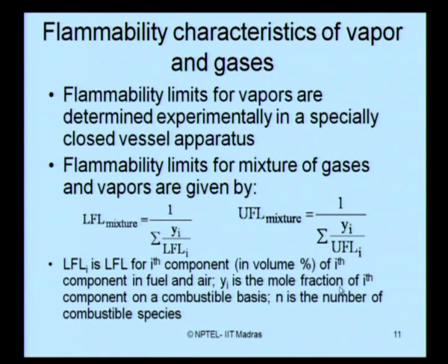So, if you have different mixtures, if you have the mole fraction of any component on a combustible basis, and if you know the volumetric composition of that in percentage in fuel and air, using this relationship of LFL and UFL for any given mixture, you can easily obtain the upper and lower flammability limits respectively for that mixture.